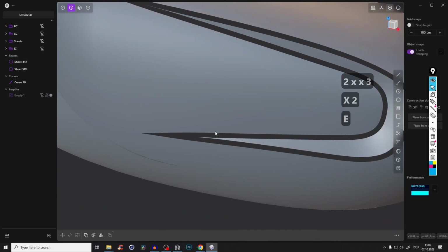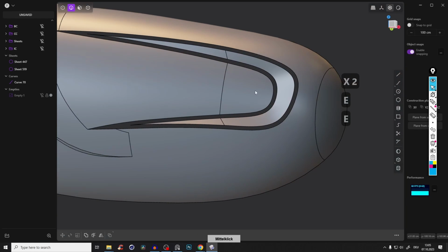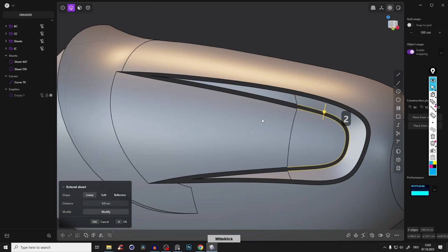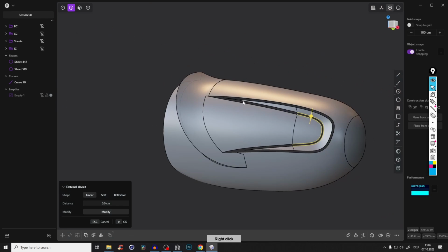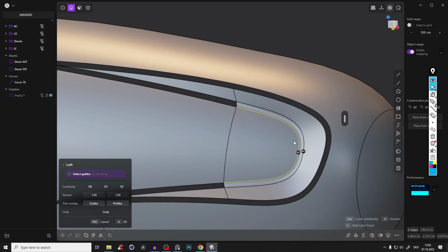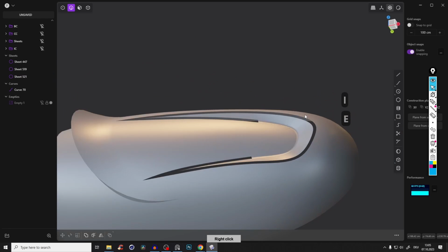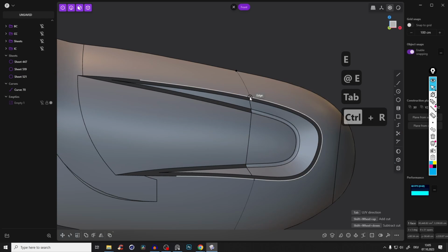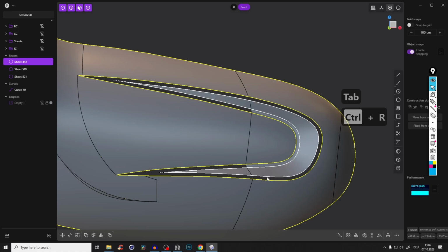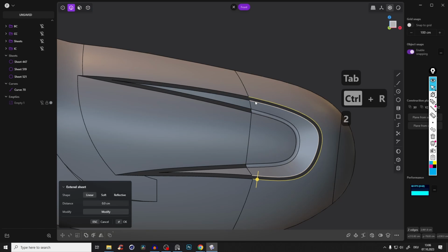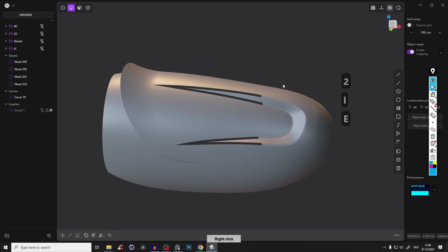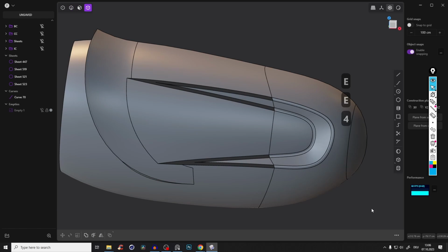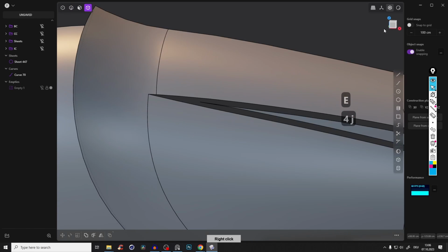So we have something like that and let's do some magic. So why did we do this? Because if that will not work out with the fillets, you can basically just loft that with G1, and you see we basically have a fillet inside. And the same here, so we have to break this surface up here again. So we always have the same length of the edges and loft that, and you see it's absolutely beautiful. So now let's press 4 and join first everything before we continue.